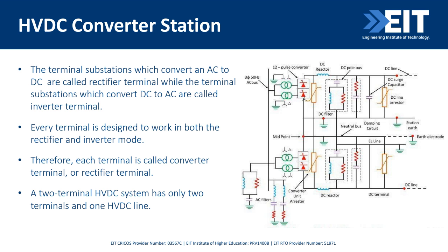So the converter station, as we discussed, is the major cost factor in HVDC transmission because a lot of work is done at the converter station. That's where we step up the voltage and then convert it to high voltage DC, and that's where we maintain the power quality as well. Like we have filters there to get rid of any harmonics or ripples.